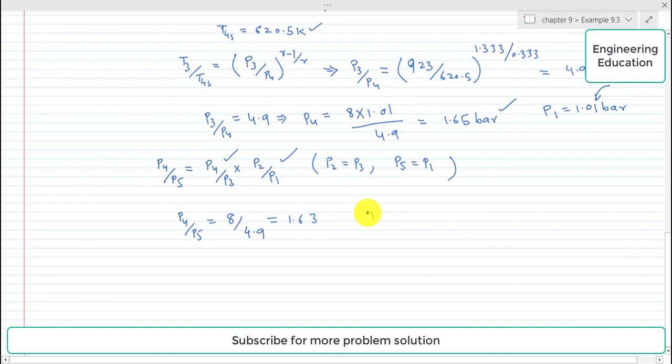So again, using the expression of temperature ratios and pressure ratios relationship for the low pressure turbine, we can write T4 by T5s is equal to P4 by P5 power gamma minus 1 by gamma. So putting the values, P4 by P5 is basically 1.63 and the gamma value is 1.33, so it will become 0.33 over 1.333. Simplifying this and putting the value of T4 in the expression, T5s comes out 588 Kelvin.